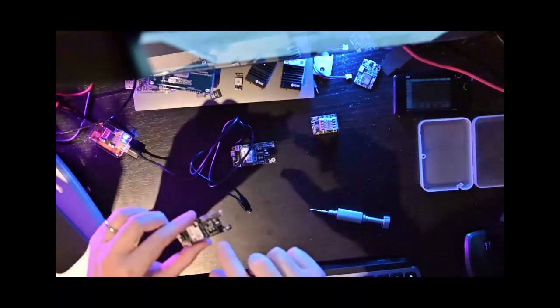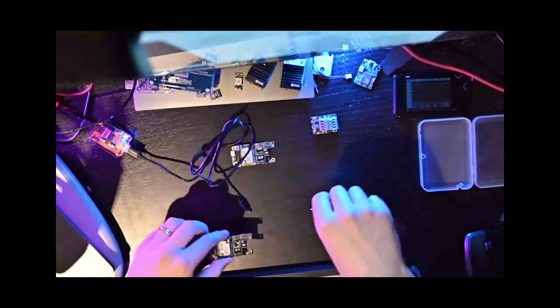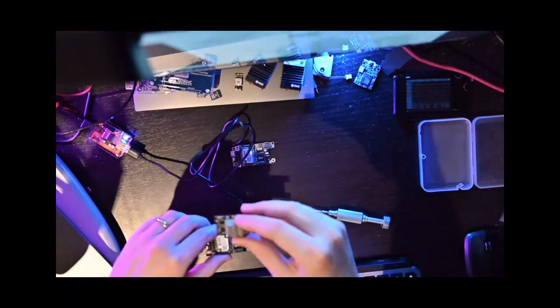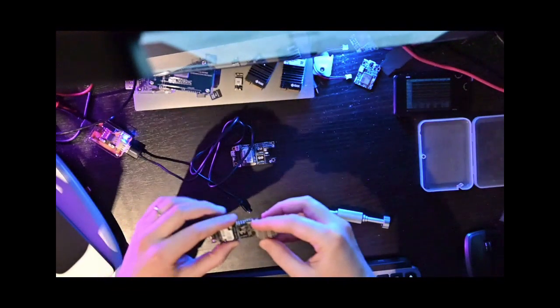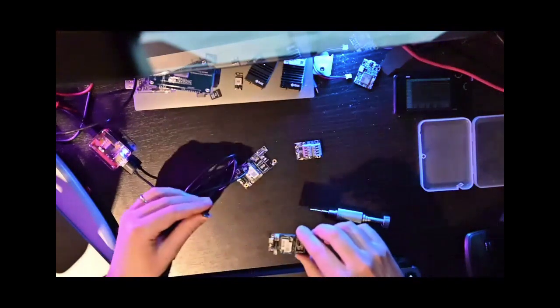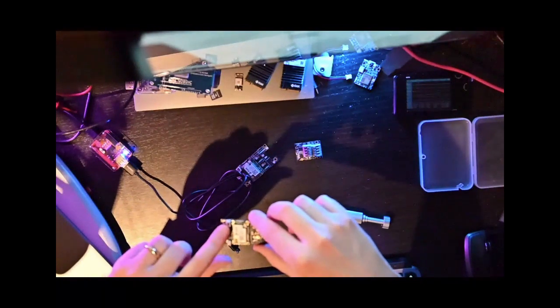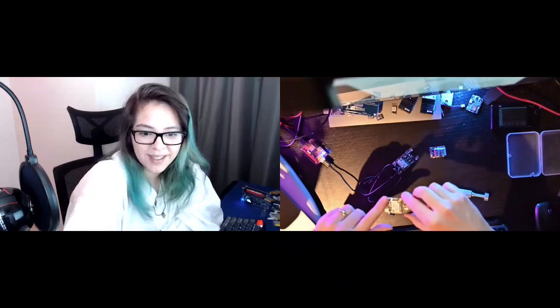Okay, so I've got my BME 680 sensor. This is the sensor we're using for the workshop. You can obviously have other sensors. So here I've got the Modbus interface, for example, which will go on the WisIO block, but I'm not using that now. So now that it's ready, I just need to connect it to USB. The board can be powered from USB, from a LiPo battery, and also from solar. The solar will charge the LiPo battery.